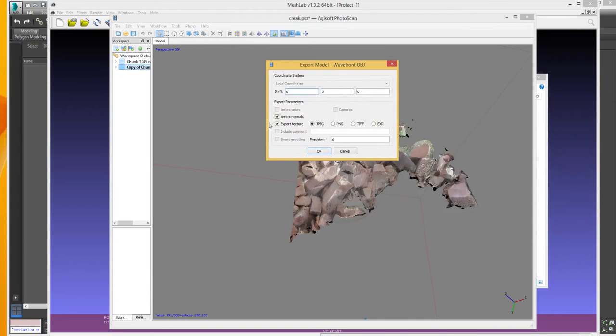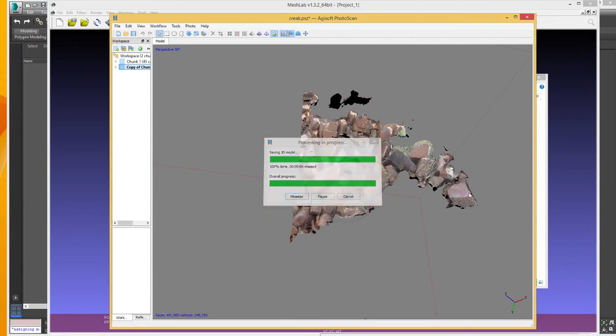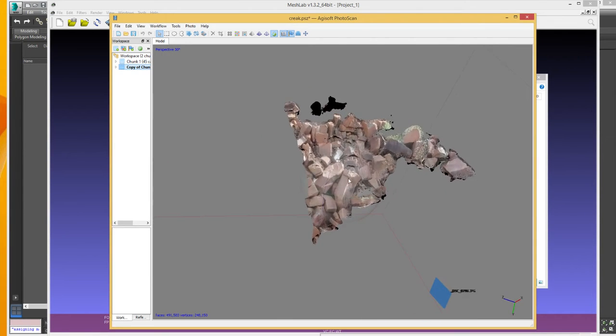And we do want to export the textures, that's the important bit. So we've generated that texture. That's going to form the basis of the base image that gets projected onto the low poly as well. So these pixels are going to get projected onto the low poly version. We hit OK. It exports the image along with information about the mapping of the texture and the texture itself.